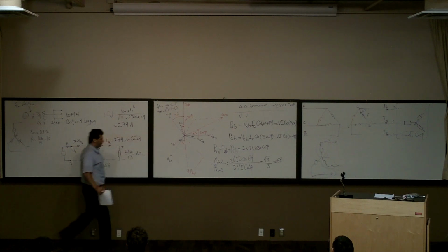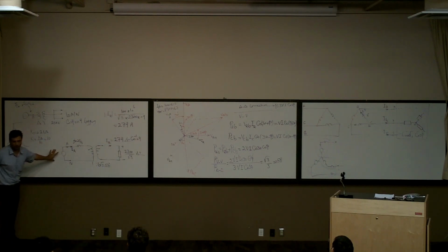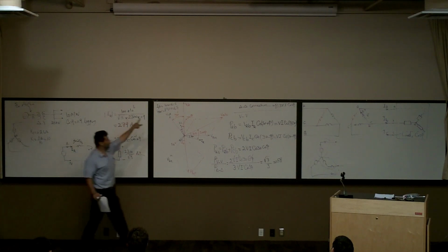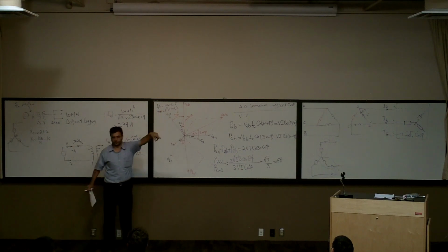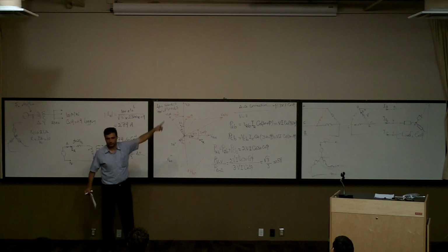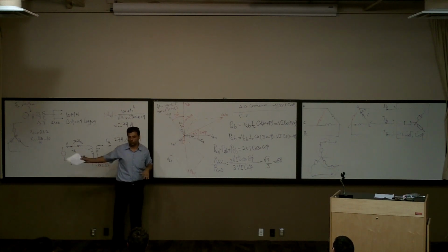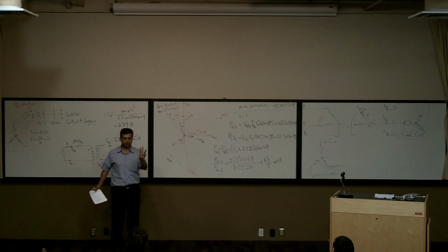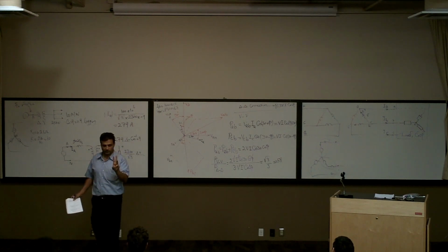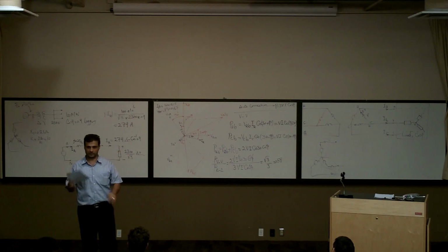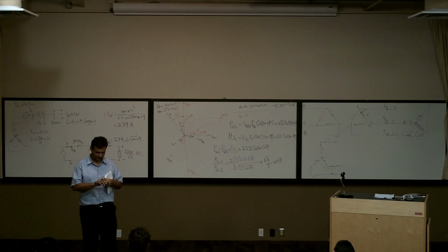How much is the active power for one phase of this? It is VI, 100 times this times cosine phi. How much is the Q? VI sine phi, right? How much is the total S? 3P plus 3jQ, right? Because this is per phase we are following. 3P plus 3jQ is 630. Now, the reason I didn't write it down